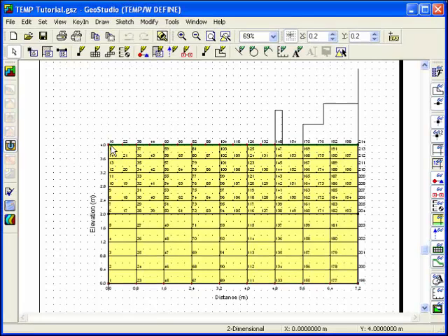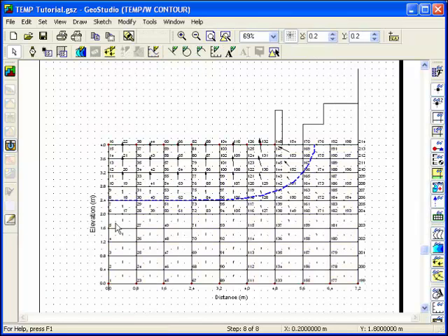The primary objective of the thermal analysis was to determine the depth of the frozen zone under the ice surface after the ice had been in place for 18 months. You can view the results directly by clicking on the contour icon in the Analysis toolbar. By default, the results for the last time step will be shown, including the location of the freeze-thaw line. To view the results for all the time increments, choose Time Increments from the View menu.